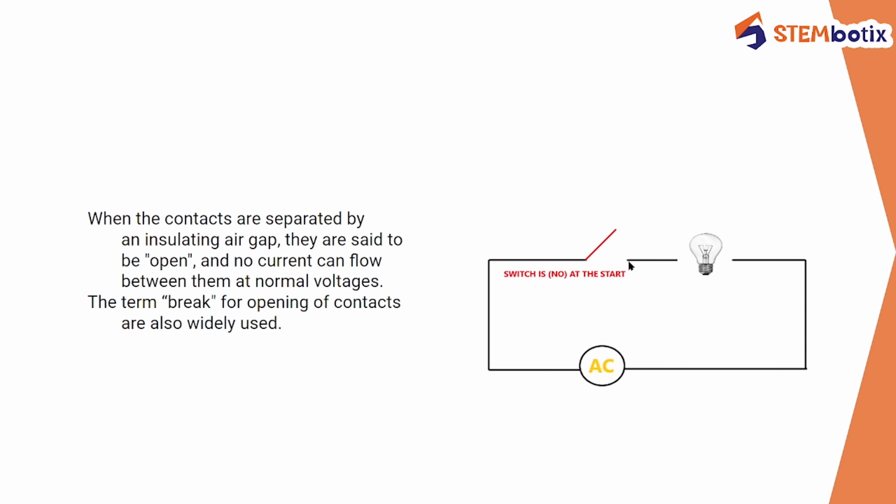A switch with both types of contact is called a changeover switch or double throw switch. It means a single switch is able to break the circuit and make the circuit. So this kind of operation is changeover, meaning it can change from one to another. These switches are known as changeover switches or double throw, meaning they provide two paths alternatingly.